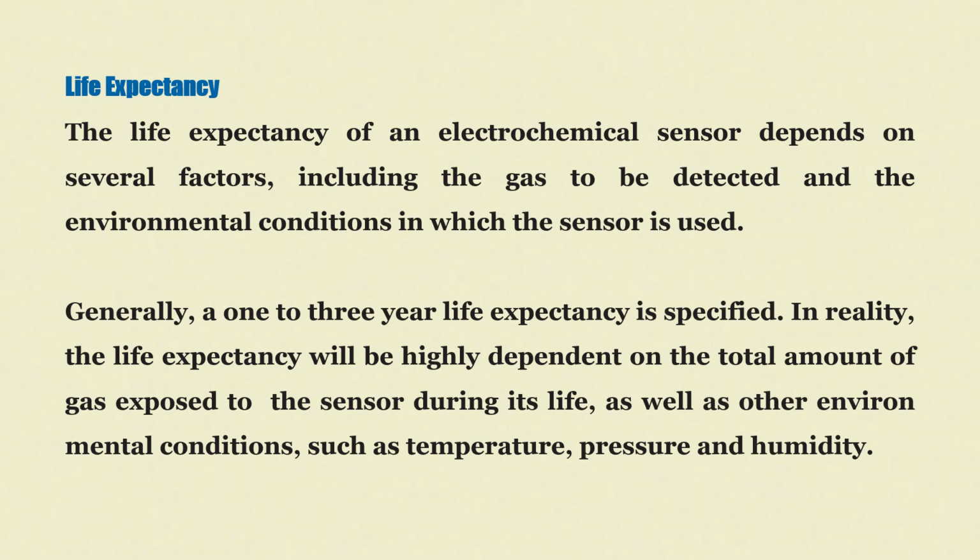So, what is another parameter that we have to worry about in sensors? It is the life expectancy. The life expectancy of an electrochemical sensor, as I told you, depends upon several factors, including the gas to be detected and the environmental conditions in which the sensor is used. Sometimes very harsh environmental conditions require frequent substitution of the sensors.